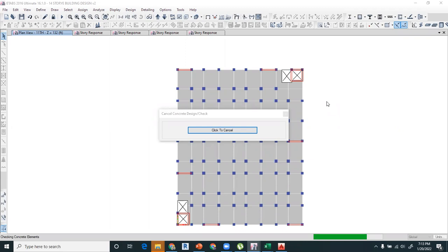Yes, it's much easier. So there will be no earthquake in your load combinations, and you have to select those combinations accordingly for the design of the frame, the slab or shear walls. There will be no issue in the drift, and no issue about where to put the shear walls. But if you are designing for seismic forces, then you have to go for shear walls, torsion and drift, all of these.